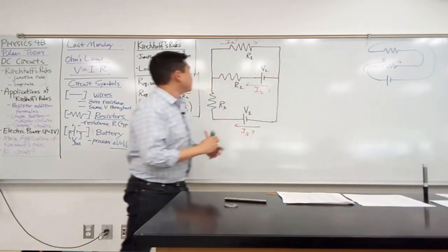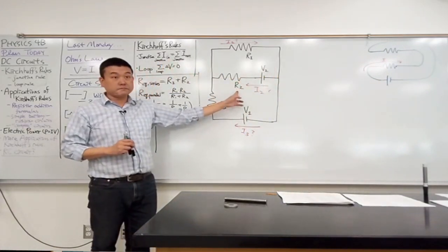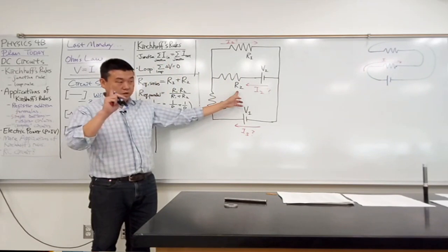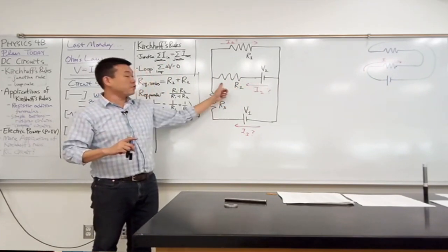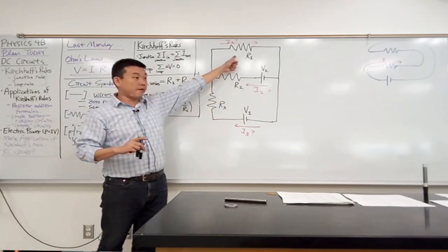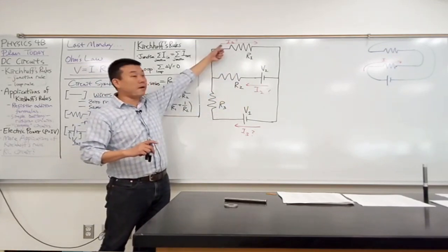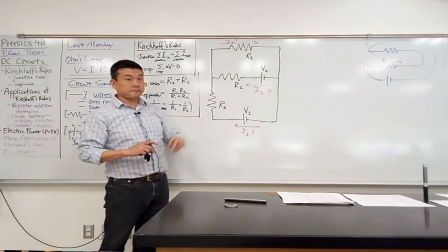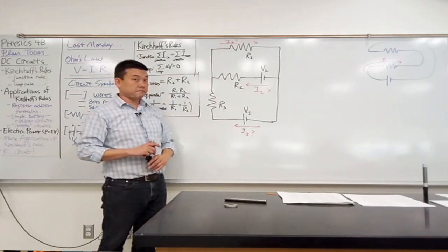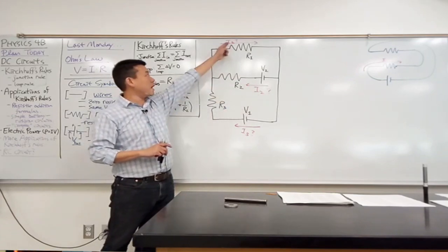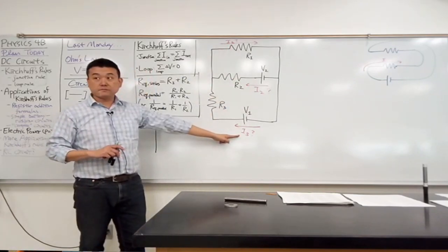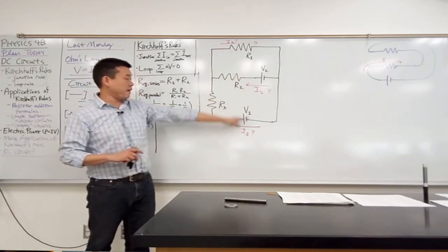So in that sense, is R1 and R2 in series? Look carefully. Current that's going through R2, must that flow through R1? As in, can you say that I2 must be equal to I1? Look at it carefully. If you are saying I2 is equal to I1, what are you saying about I3? If you are saying I2 is equal to I1, what is I3?